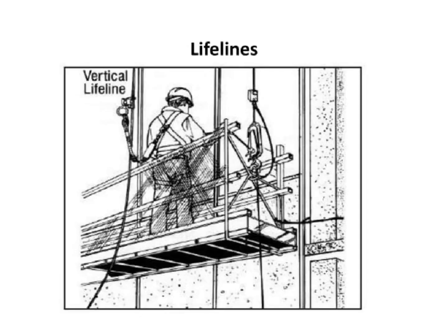A lifeline is an important safety feature for working at heights and is used to help keep workers secure. One type of lifeline is a vertical lifeline, which is a vertical rope that is connected to the worker's harness and anchored at the top of the structure. This type of lifeline helps to support and secure the worker, preventing them from falling. It is important that the lifeline is kept free of entanglements and properly installed, as it is the primary safety feature.